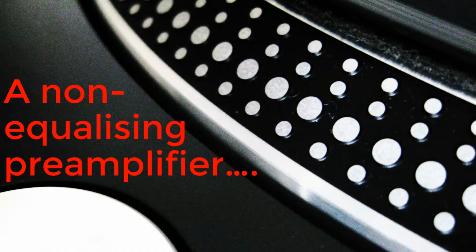Now, just as the signal from a gramophone pickup is too small to apply to the line input of most amplifiers, so it's also too weak to apply directly to computer sound card or audio interfaces. So although we don't need an RIAA equalising preamplifier, we do still need a dedicated phono preamplifier to bring the small signal from the cartridge up to a healthy level for the input of the computer sound card. We need a preamplifier which provides gain and impedance conversion without applying the equalisation.